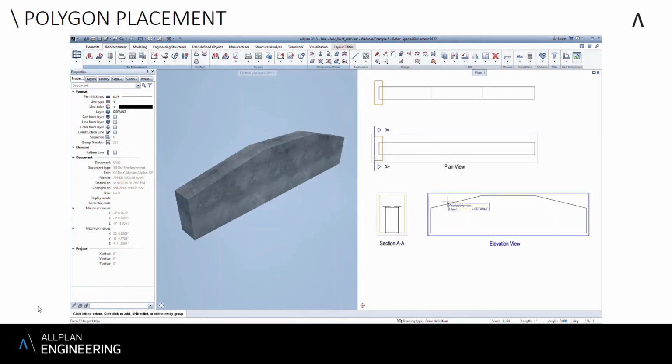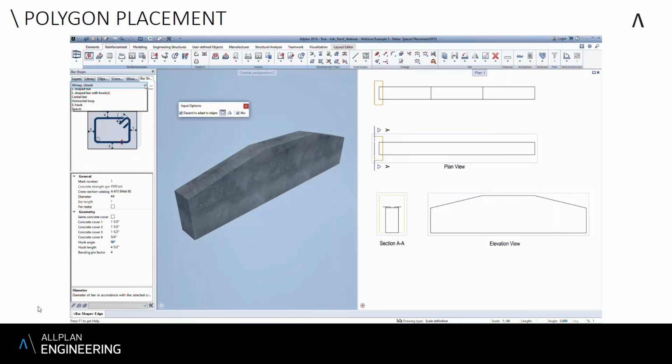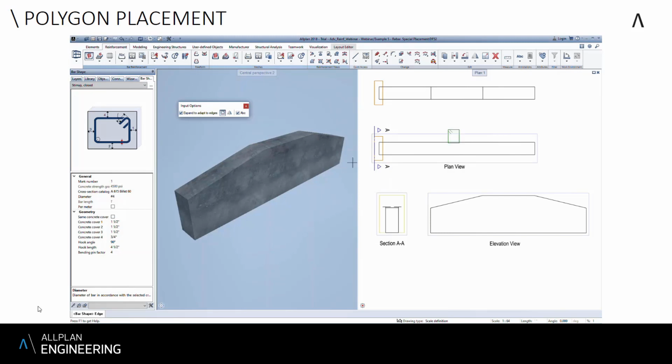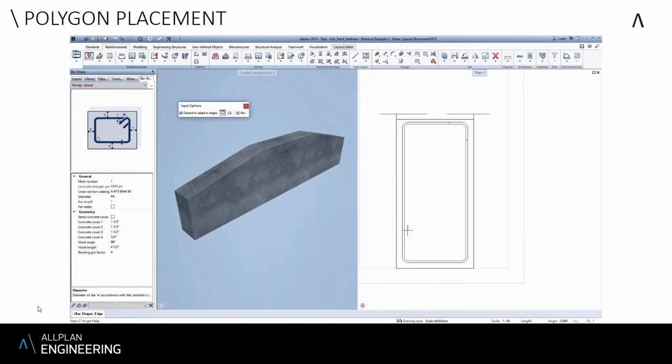You'll see a typical workflow is that we really define several sections and profiles of whatever it is that we're going to reinforce, and then we use those to reinforce the section. We have several built-in rebar configurations that you can choose from to start off the detailing, and there are also freeform options available. The program can identify the extent of the structure that you're detailing, so the bars will expand or follow the outline of whatever it is that you're reinforcing.